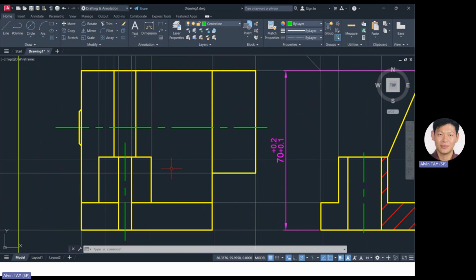The height of the boss. So this split happens all the way to the boss height. You must draw the line across. After that, find out the diameter of the boss. From the plan view, you draw a line down to the diameter of the boss. So this is the boss, the split.